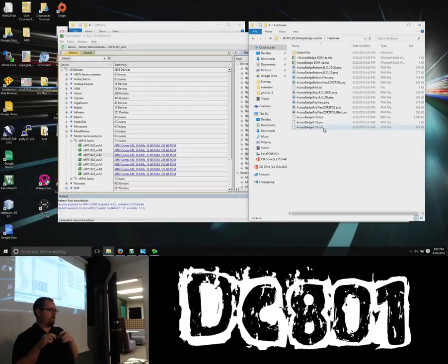The charging circuit will also, if you unplug your battery, run the badge off the micro USB somewhat. So it will down convert. The battery runs at 3.7, and the battery voltage goes straight to the RGB LEDs, not the orange LEDs, while it down converts to 3.3 for the chip. Oh wow, so we have a down converter in there too. All that circuitry's there.